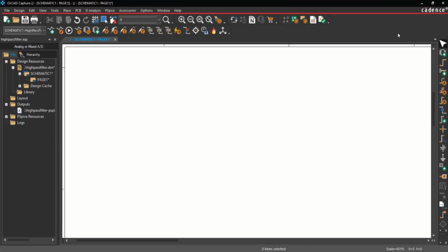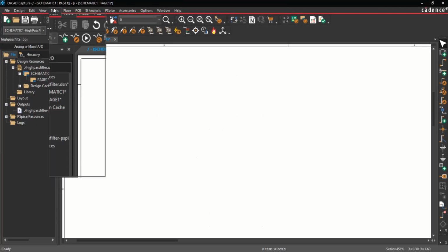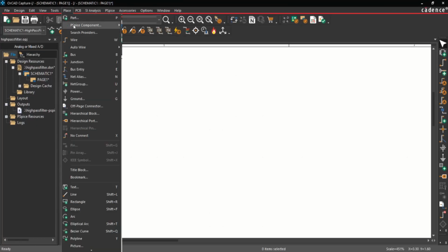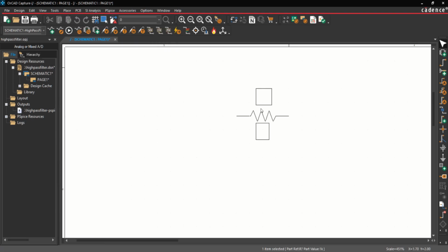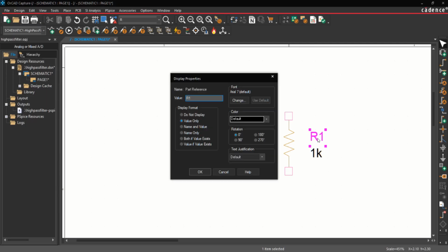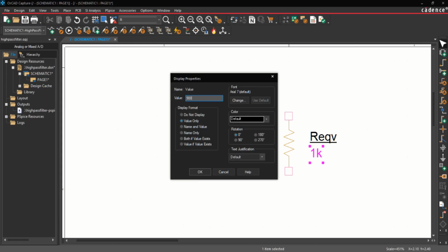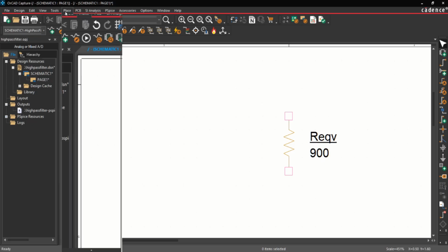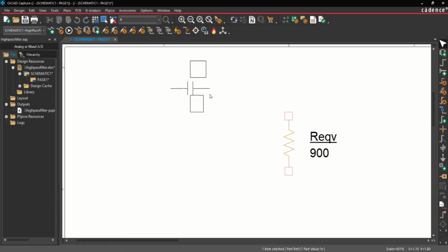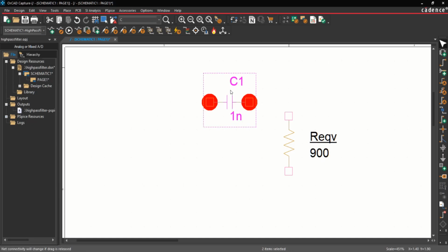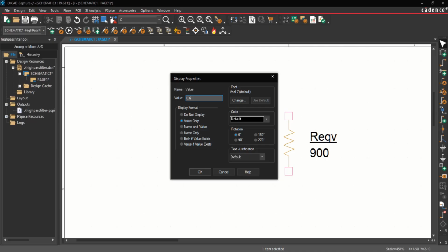Now, let's go into our simulation software and create the circuit. First, we will place the resistor and capacitor in series. We will connect all components with wires. Next, we will assign them proper values. Next, we will insert the AC input source, define its parameters, and tidy up the schematics a little. The process is pretty self-explanatory, so you will not have any problems recreating this circuit in any simulation software.